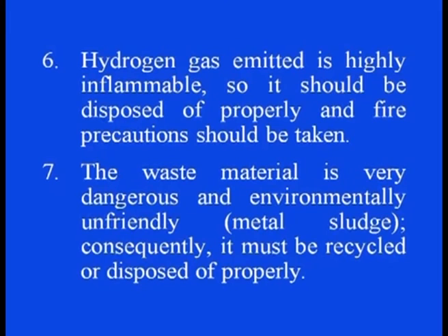Number 6, hydrogen gas emitted is highly inflammable. Therefore, it should be disposed of properly and fire precautions should be taken. Number 7, the waste material, which is nothing but metal sludge, is very dangerous and environmentally unfriendly. Therefore, it must be recycled or disposed of properly.